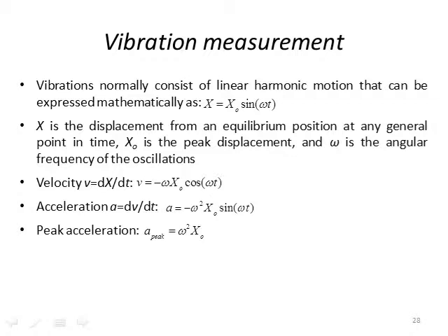So in a vibration measurement, you've got this mass vibrating with some fundamental frequency, and it's connected to the housing. Now when the housing gets an acceleration because it's connected to a larger system, that acceleration is going to be coupled from the housing to the mass through the spring and the damper. Okay, remember that. Then the velocity we can calculate, the acceleration we can calculate, and also the peak acceleration we can calculate.